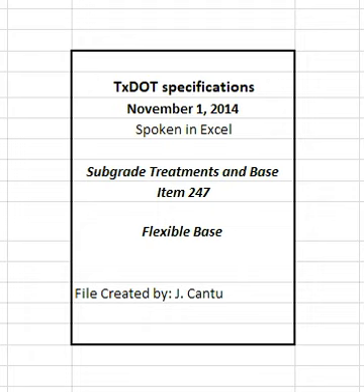6. Payment. The work performed and materials furnished in accordance with this item and measured as provided under measurement will be paid for at the unit price bid for the types of work shown below. No additional payment will be made for thickness or width exceeding that shown on the typical section or provided on the plans for cubic yard in the final position or square yard measurement. Sprinkling and rolling, except proof rolling, will not be paid for directly but will be subsidiary to this item unless otherwise shown on the plans.